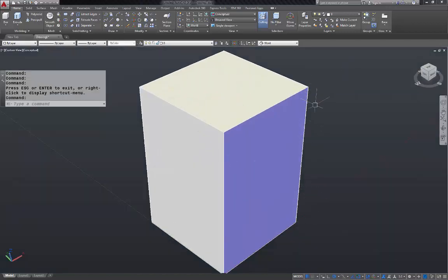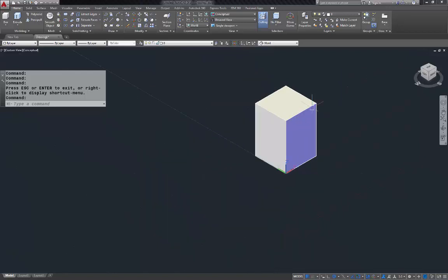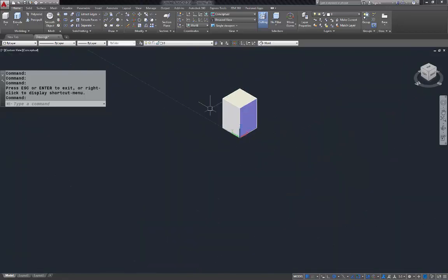Now, notice how the sides are tapered here. Can you see that? That has to do with how we're viewing this. If I go over here to the little house and right-click on that, it's right now in perspective, which personally I don't like. Some people do, and if you do, you can draw that way. It's great. But I'm going to go into parallel. And to keep it in there, I'm going to set current view as home. Now it'll always stay in parallel as opposed to perspective. But at any time you can go back and change it.